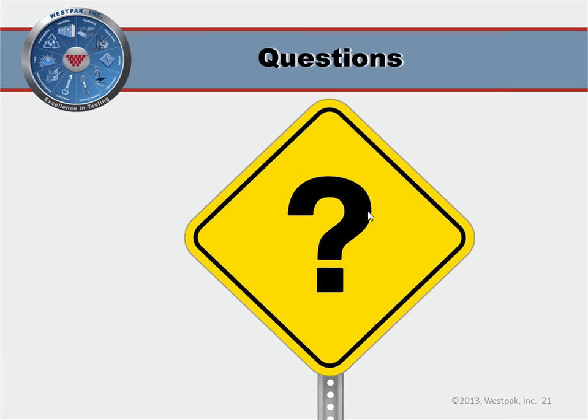We call it the amplification level Q, and we've seen Q values in the neighborhood of 50 to 100 times, depending on the damping of the individual system. So the reason that we want to understand resonances is they're killers. They're really killers. So Herb, how do we find resonance in the lab? How do we do that?